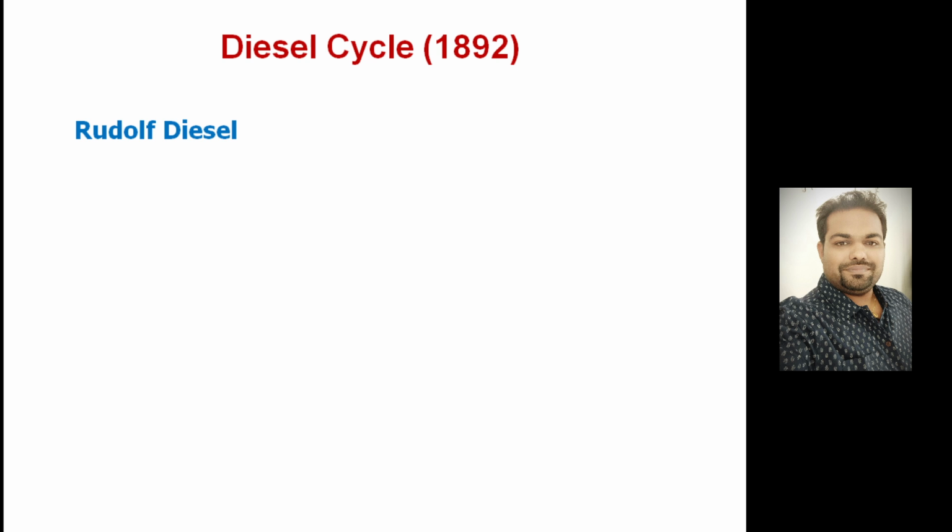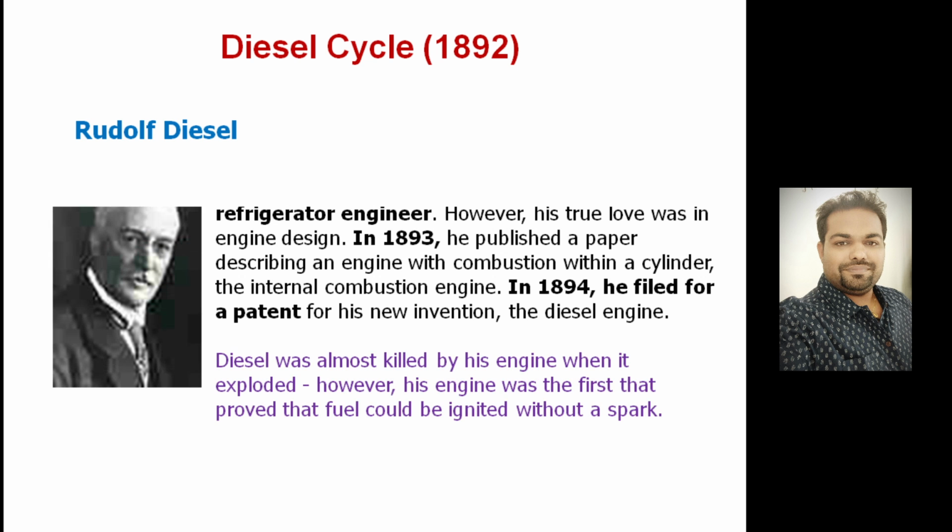Then once we have reached a certain temperature, we can use a high compression ratio so that the temperature of the air becomes greater than the self-ignition temperature of the fuel. The moment you send the fuel inside, combustion will occur, combustion will start, and your process follows. Mechanical work you can get. That means diesel engines do not require a spark plug. That's one advantage. And the process will be slightly smooth because you are compressing only air here, so there is no problem of pre-ignition or detonation in the engine. But in the case of the petrol engine, that is a big drawback.